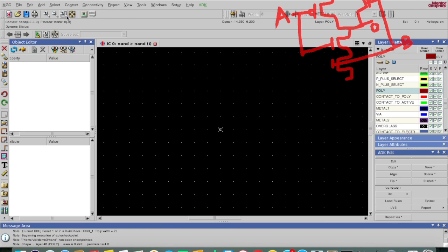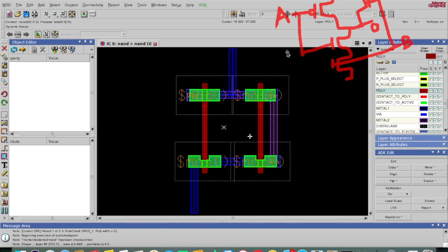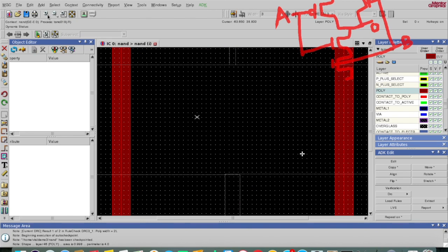Next thing I'm going to make the ports, for inputs A, B, and for output O, and the power, VDD and ground. So for that I will make ports. How to make these ports? For that I'll again zoom in. Maybe I'll make one port here. I'll use metal 2 for making ports and I'll press this rectangle. As you know, the minimum metal size I can draw is 3L. So I can draw a port of minimum 3 cross 3.